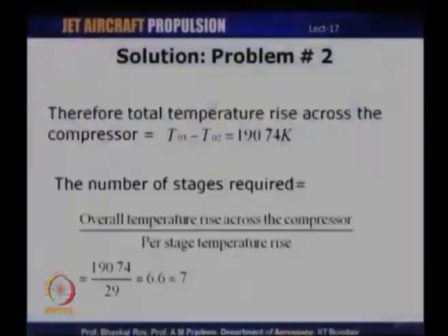The second part of the question is to find out if this particular rotor is likely to suffer from any shock losses. So, in this case we will find out the relative Mach number and see if it is greater than unity. That would mean that the flow at the exit is likely to be supersonic, which means that there is a likelihood that shocks will be present and therefore shock losses. So, let us go back and look at the velocity triangle once again.